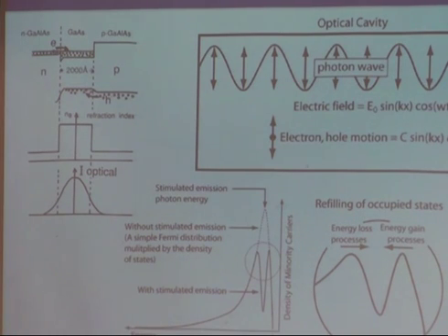The other very big advantage of the double heterostructure laser is, as we talked about earlier, that a small band gap region has a larger refractive index, right? So this is a refractive index plot now. But light wants to be in regions of lower refractive index. Basically, from Maxwell's equations, I think you know that the energy of light goes as half epsilon E squared, and you can do the math here. Essentially, you will find that if you have two regions of different dielectric constants, the intensity is maximized in the region of lower refractive index.